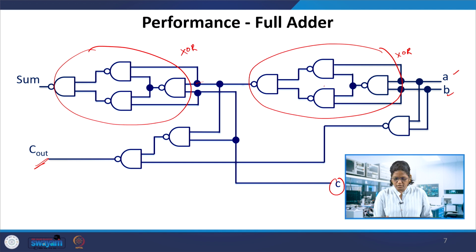So the idea here is to reduce the time for the ripple carry, that is, how much time it takes for the carry to ripple through when calculating the sum and the carry. Here we can see from AB to sum, and carry to sum. The carry to sum has 1, 2, 3, so 3 gate delays. A two-input NAND gate is considered to be 1 gate delay.